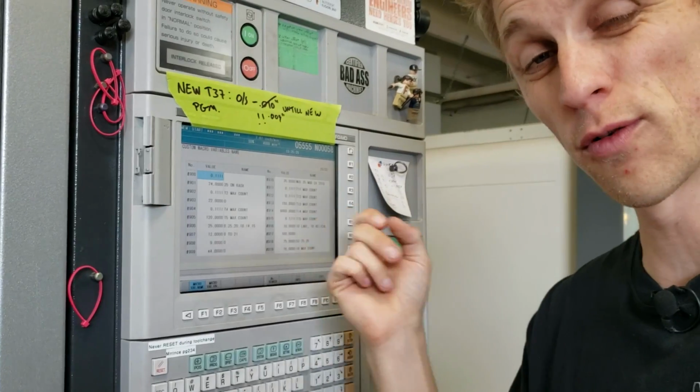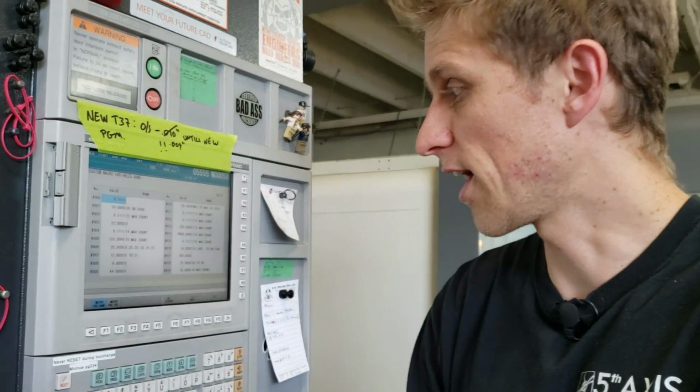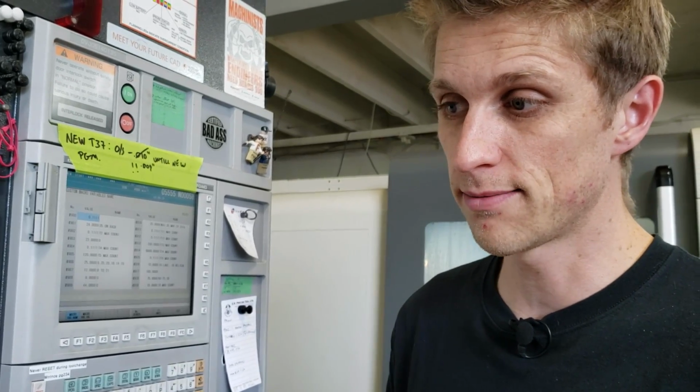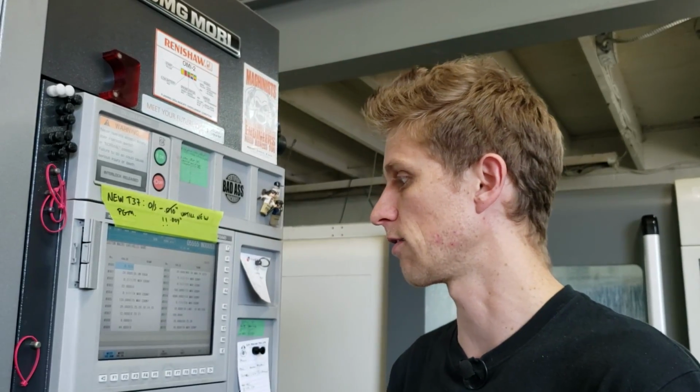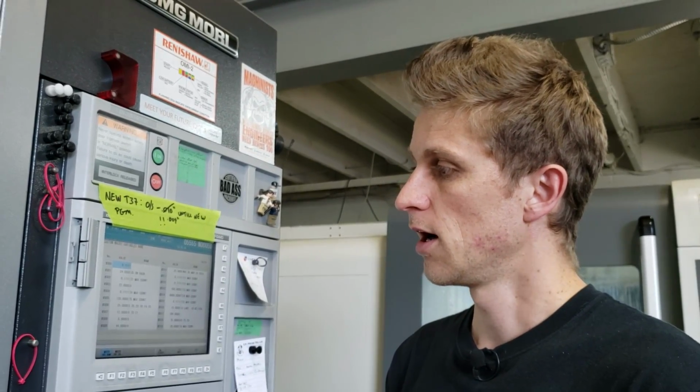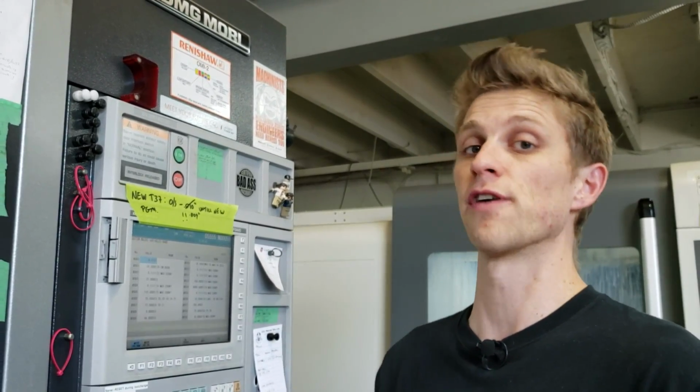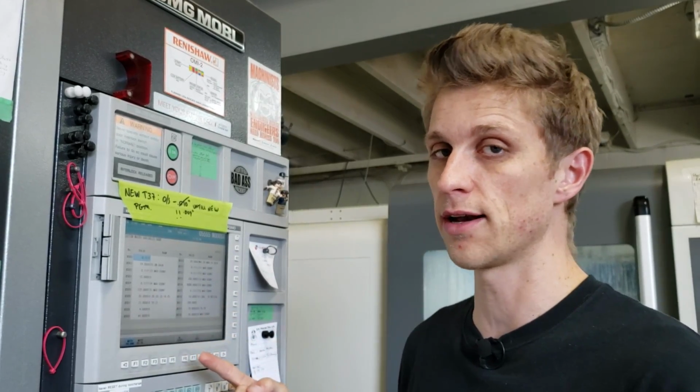I've been tracking this for over 2 years. So I know that 12 pallets is a good number, because I've tried 20 and it didn't work, or it breaks at 17. So I want to set it below the breaking point where it's happy. I'd rather replace it early when it's good, as opposed to stretching it out and making bad parts, making bad holes or whatever. Conversely, if you pull it out too early and you look at the tool under the microscope and it looks perfect, you know that you can stretch it a little bit longer in the 900s.